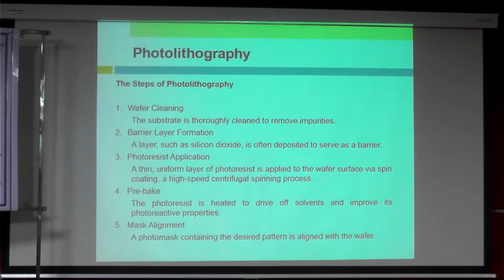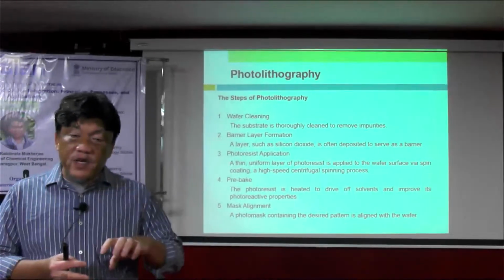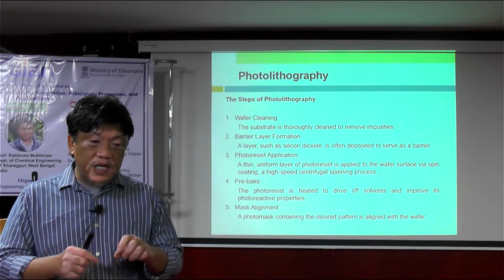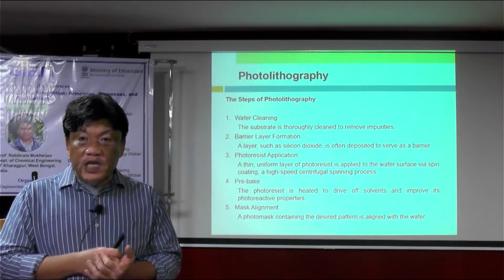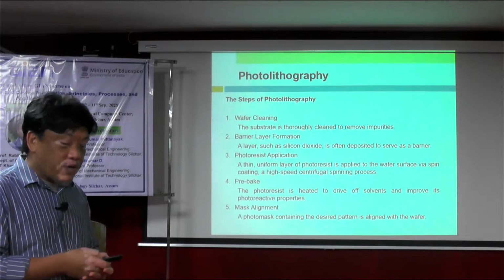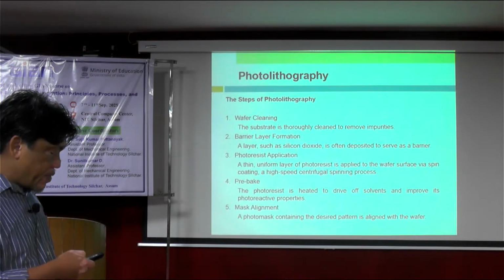If it's on the substrate itself, then the first alignment is just to make sure it's maybe at the center of the photoresist, the wafer, etc. But the subsequent processes normally need careful alignment, because the process will determine the structure, what you want to produce. If you have a pattern and then you want another pattern, it must be aligned accordingly to make sure that it is at the right position. So the mask alignment will be very important.